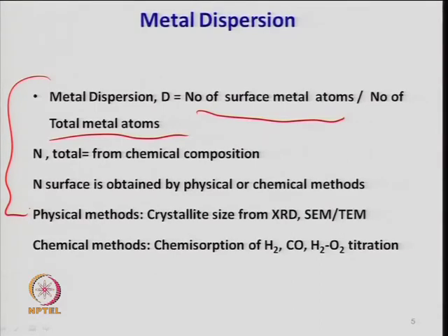Physical methods, as I said, can be used to measure this. Crystallite size you can calculate from X-ray diffraction, which we will talk about later. Similarly, with scanning electron micrographs, you can take pictures of the metal surface and see the crystal size, morphology, and topology of the surface.